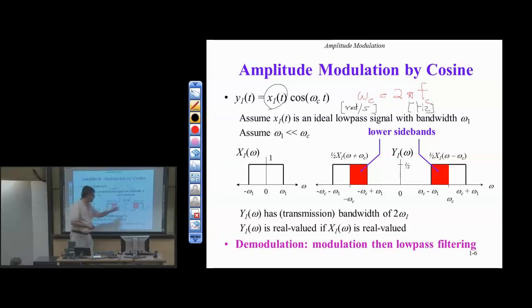On the receiver side, we're going to receive the bandpass spectrum, plus noise and other things we don't want to keep around. So what we'd like to do on the receiver side is to take the bandpass spectrum and go the other way, go back to baseband. And we can do that by applying, in the case of sinusoidal amplitude modulation, multiplying by a cosine and then low-pass filtering to pick off the baseband spectrum. Let me try to draw that for you.